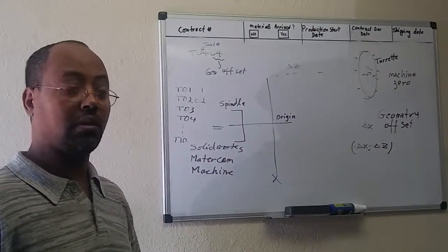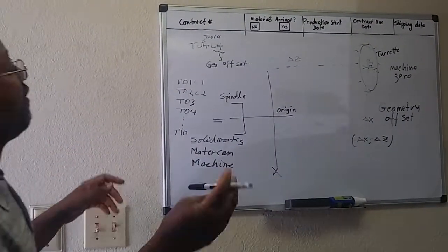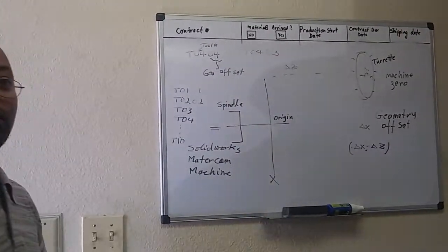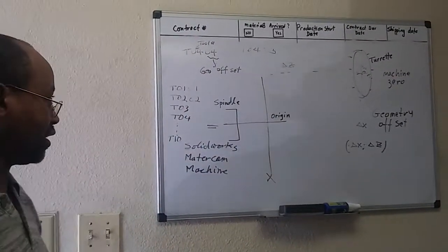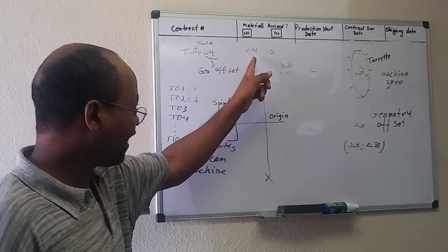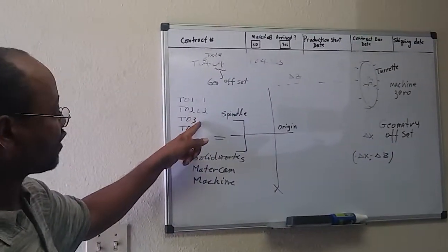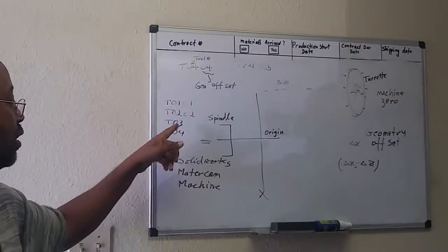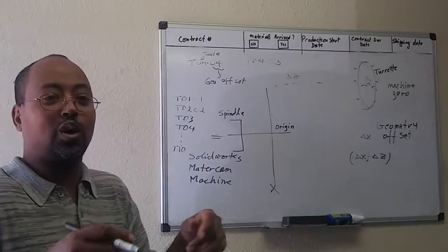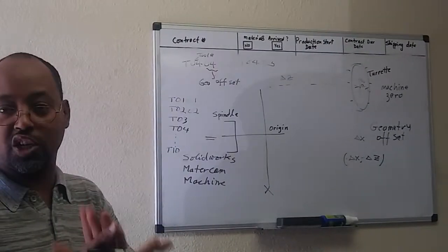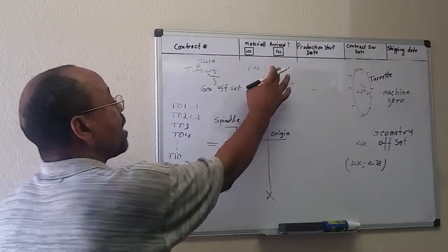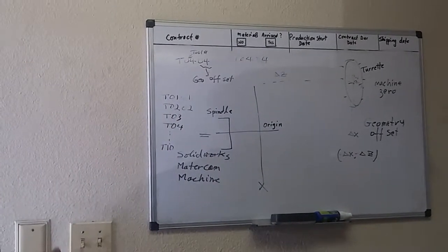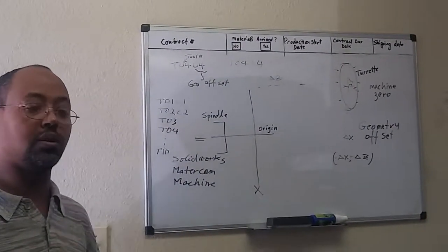You would never call something like T0403. It doesn't have any meaning, because you're saying tool 04 with offset 03. You're trying to use an offset for tool number 3. That's mixed, because tool number 3 has its own shape, its own insert. They don't have any kind of relationship. So this is always the same number. It's T0404. Or if I want to select tool 3, it's T0303. That's how they're called in the program.